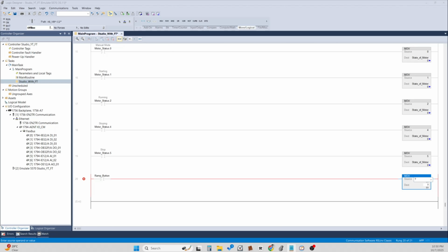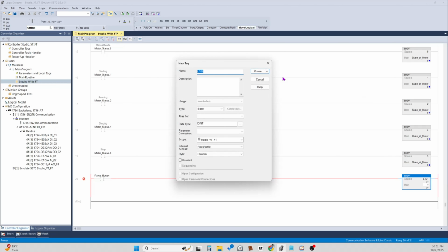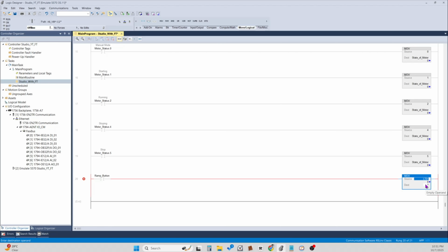any plant, and in the plant you want to maintain the temperature, or any pipeline, in the pipeline the set point for the oil or something else, making real flow data. So here you need to create an integer tag, for example LT0, which means level transmitter 0. Right click, here you can see new tag, click on tag, and the tag is created.